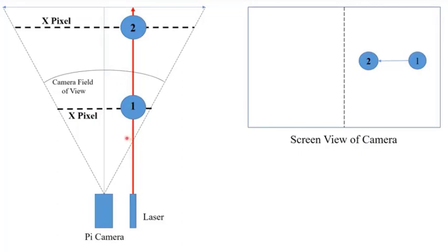The angle between the object's return and the camera's central axis can be calculated with the measured pixel position on the return, and this angle can be used with the known distance between the laser and the camera to calculate range. In order for my LIDAR system to accurately collect data, it needs to be calibrated.